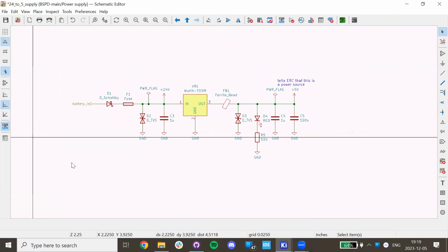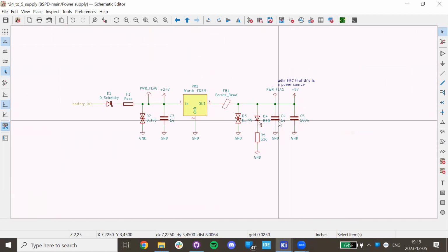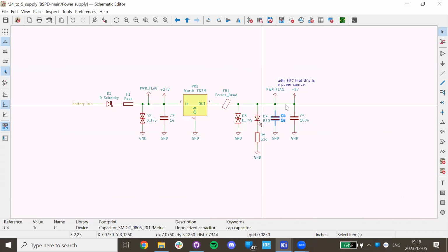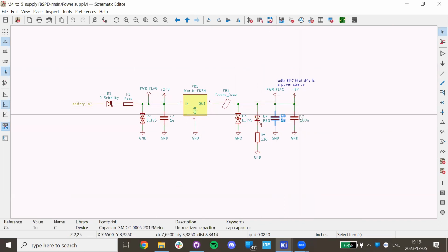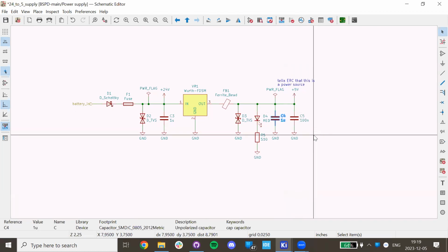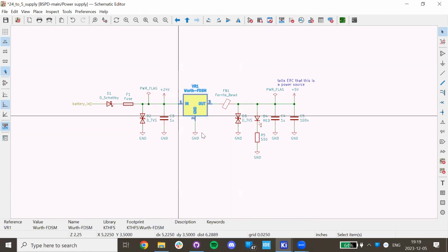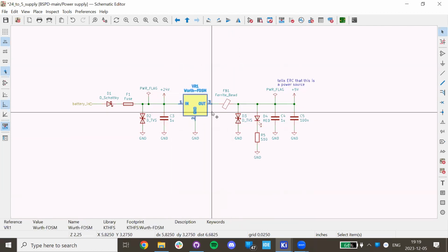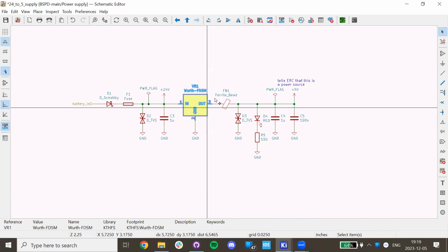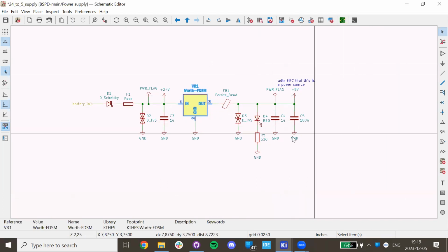We go back in the power block. These all should be close to each other, and there's a reason why we have the capacitor here. It should be close to the output of this DC-DC. Usually you put the capacitors close to things that are emitting disturbances. So this is a DC-DC, a switching regulator, power supply regulator. It will produce noise on the output.